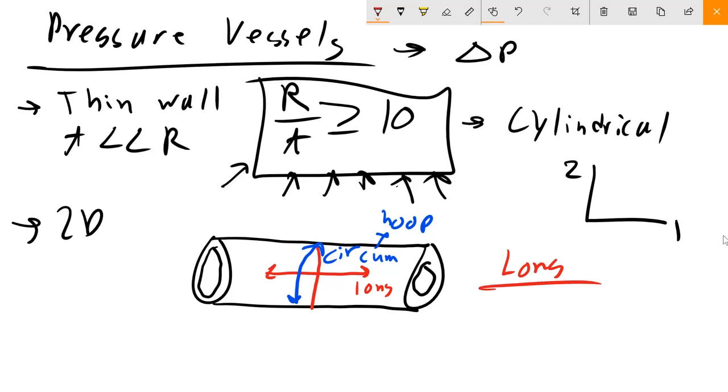So when I cut out that material, if I'm looking at the longitudinal, I'm going to have a material that looks like this. It's going to be cut, and I'm going to have my cylinder, and it's going to go around here. And now I have these two forces. Again, we want a free body diagram. We need to make sure that our forces sum to zero. So there's going to be some force emanating from this little ring here, and some pressure pushing in, opposing that cut on the interior there. Let's do the sum of the forces right now.